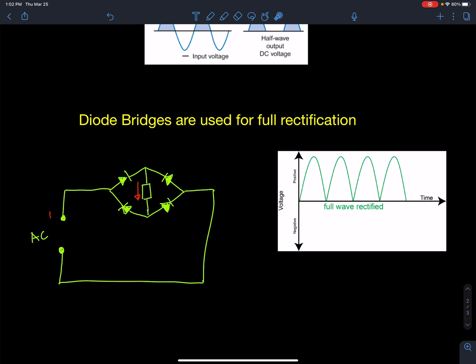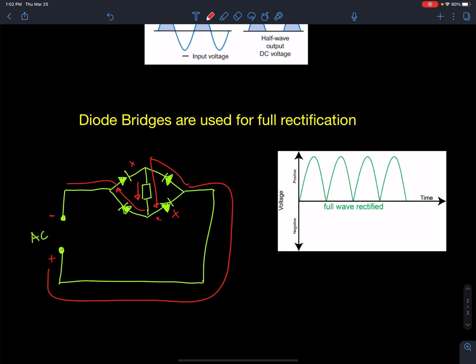Now what happens when the current switches? If the current switches direction and we're left with positive negative, let's follow the flow of the current. It gets blocked down here, it flows up, gets blocked here, so then it flows down, it gets blocked here again, so it flows out, and then comes out the other side. So even when it flips, based on this sneaky combination of diodes, the current is always going down through the device. So this device would be like the screen in your computer.